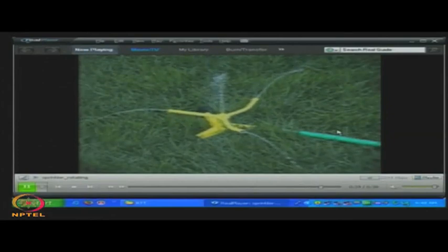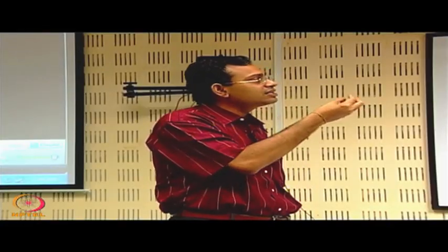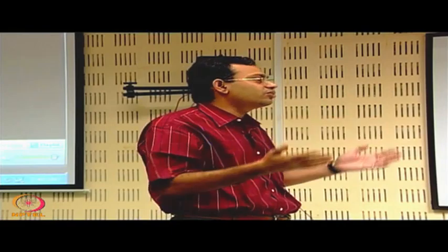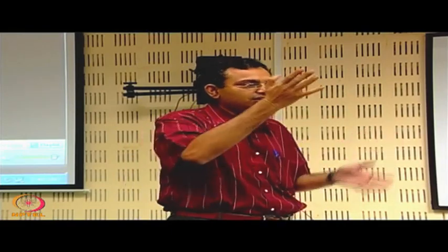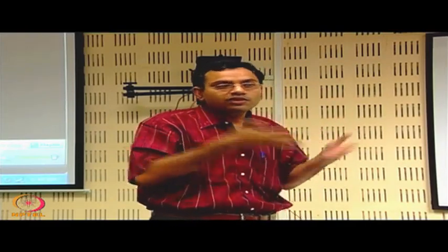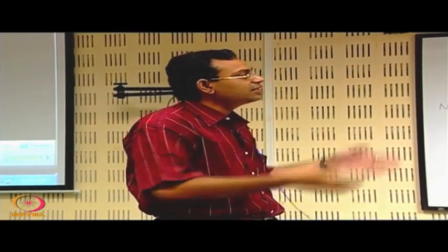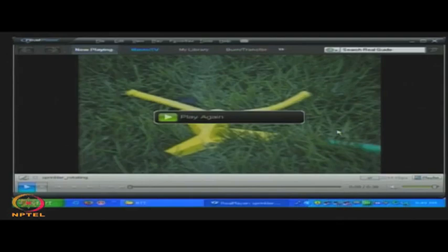That linear momentum has a moment with respect to the axis of the sprinkler. So, there is an angular momentum, and a rate of change of angular momentum that makes it rotate. Even if there is no frictional resistance, that would make it rotate very fast. Because of some frictional resistance against rotation in the pivot, it will not rotate as easily as we might think, but still you have seen in this example that it might rotate quite easily.